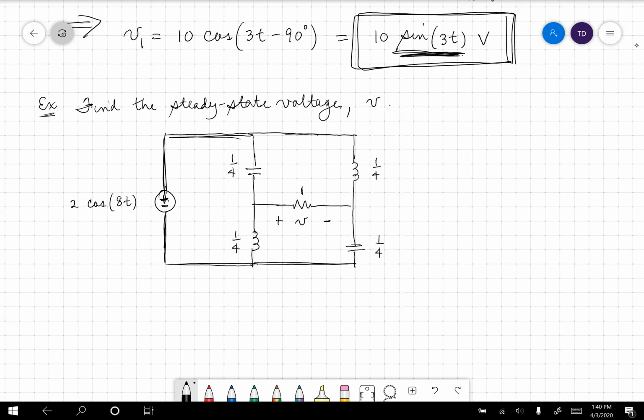We've got 10 minutes to see if we can solve this circuit. I want you to observe immediately that this circuit has 4 storage elements. This would lead to a 4th order differential equation. You don't want to have to find that 4th order differential equation. It would be nearly impossible for you to find it. That's why this phasor method is so important.